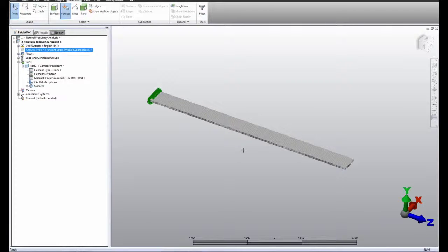The manner in which loads are applied to node points in this analysis type is a little different than in other types. We have to set up a table in the analysis parameters section based on node numbers. At this point, we need to determine the node numbers along the top edge of the beam where the load will be applied. We will use the inquire option to do this. We will also only apply the load to the corner nodes of each element. It is not good practice to apply loads at mid-side nodes when the load is to be equally divided.